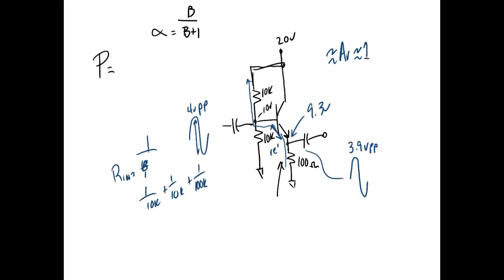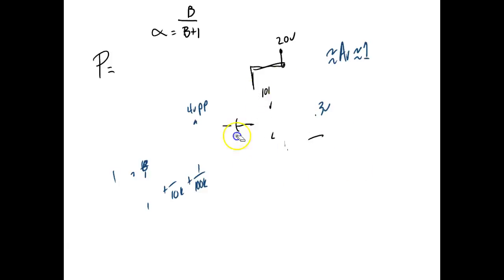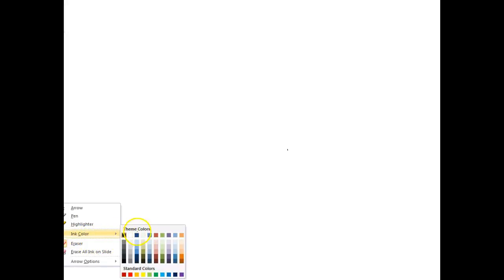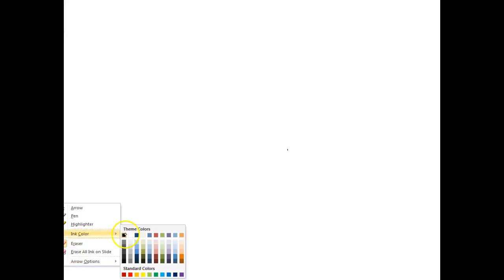So guys, these are the guys. This is what goes on in your stereo right here. But Class A is only around what? 25% efficient. You remember that? Or what's Class B? Around what? About 75% efficient. So what I can do is use 2 Class B amplifiers, and they're going to be connected common collector. So these are the outputs of your stereo right here.